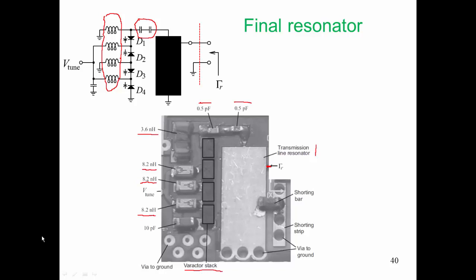Other characteristics of this microwave circuit are things that you commonly see in microwave circuits. And what we have are lots of vias to ground. If there is a spare space, we will provide a via to ground. This does two things. One is that it reduces the ground resistance and ground inductance of the vias, and in addition it suppresses the spurious parallel plate modes that could possibly exist in the substrate.